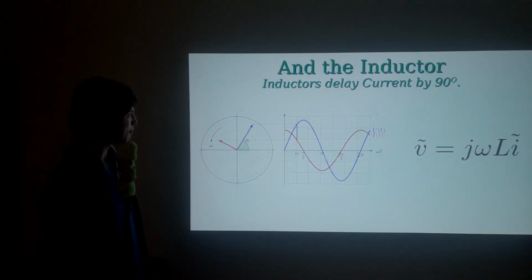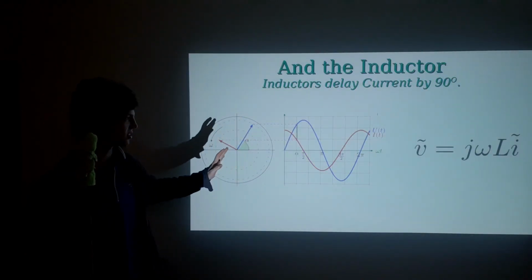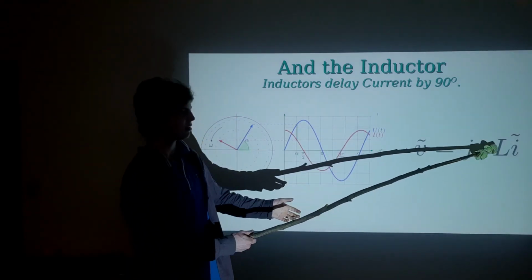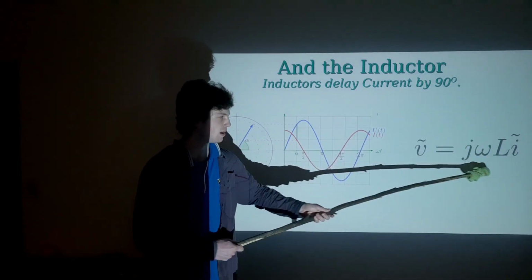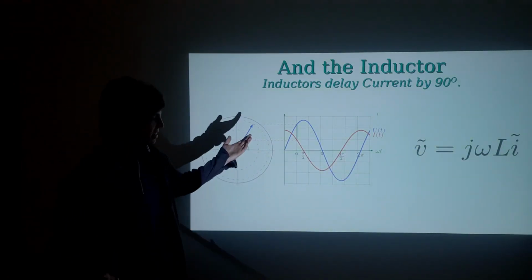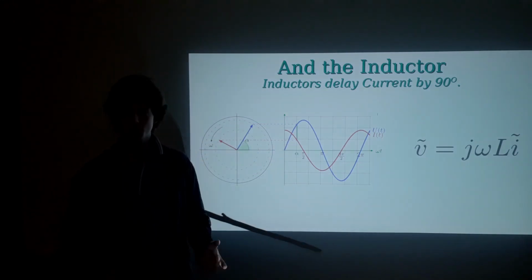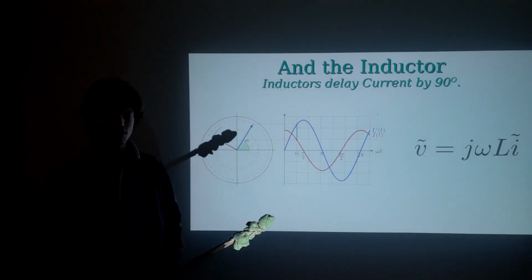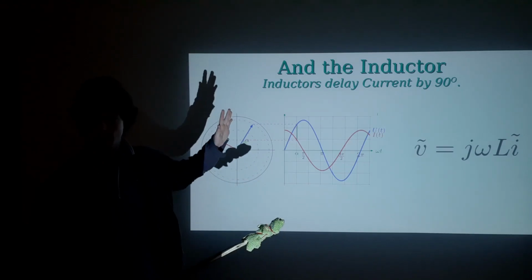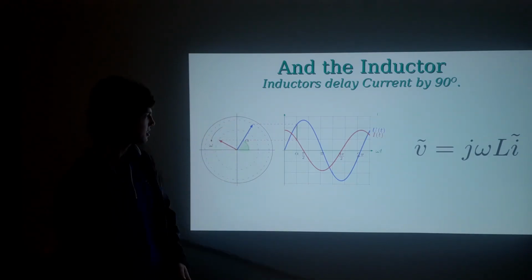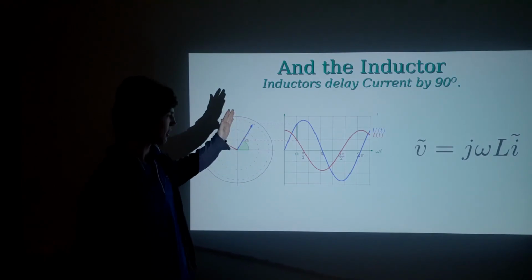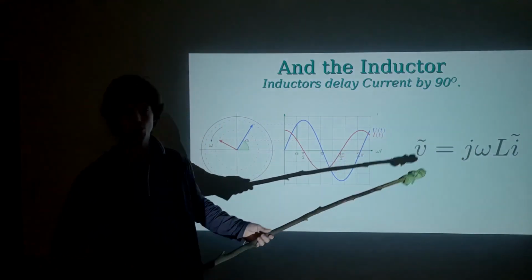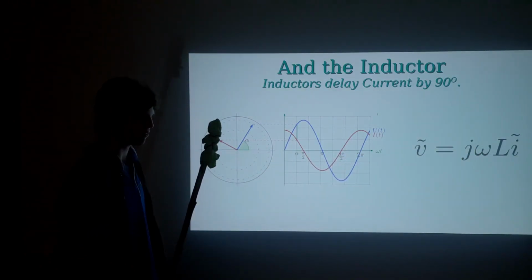Right? Now we can of course do a very similar thing for inductors. Inductors, it turns out to be the reciprocal, so V is j omega L i, and the impedance is just this bit right here, right? And as I said, inductors basically do the opposite of capacitors. Capacitors store energy in an electric field, inductors store it in a magnetic field, and from electromagnetism, those two things are very intrinsically related. So this is doing a very similar thing. All it's doing is rotating by 90 degrees the other way, right? And that's why we have our j term in the numerator here instead of in the denominator, as we had for the capacitor.